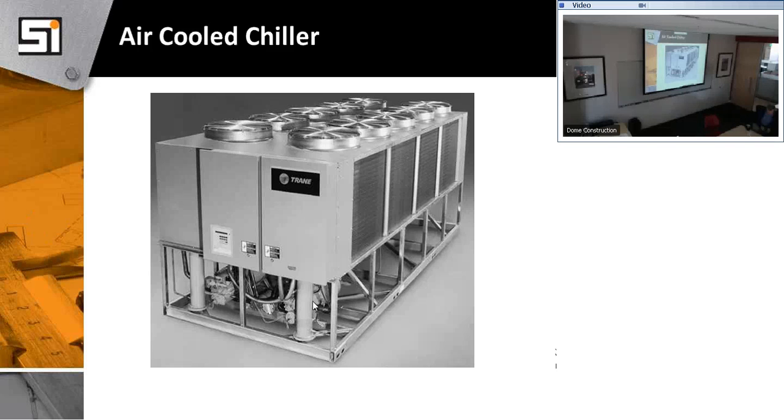It's more what I'm doing in the building, like an office building, unless it's a massive high-rise, then I just can't put everything on the roof and get it down. But if I have space, labs is where I have a lot of outside air, then we look at chilled water. Office units are pretty much all VAV package, but where I get into my labs, where I have a high amount of outside air, then I could put all this capacity in the chiller, and I just pipe it over.